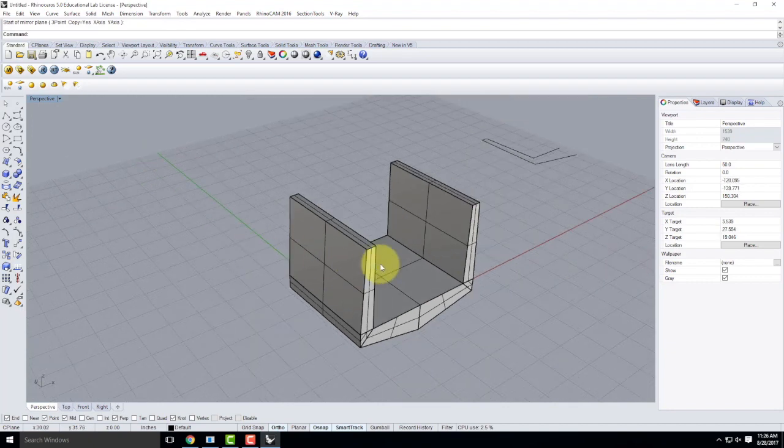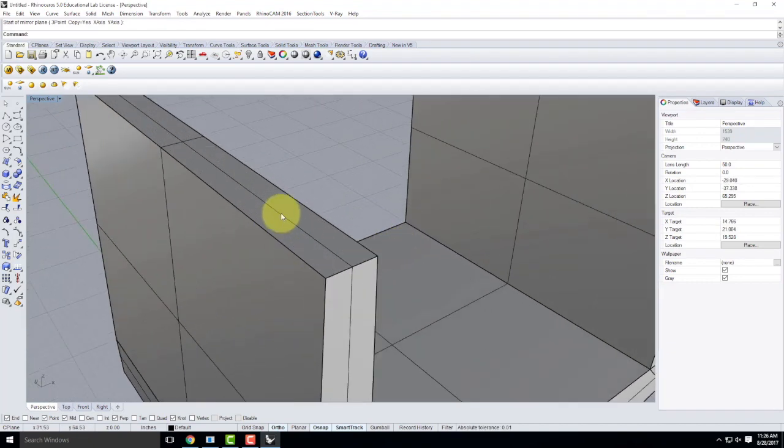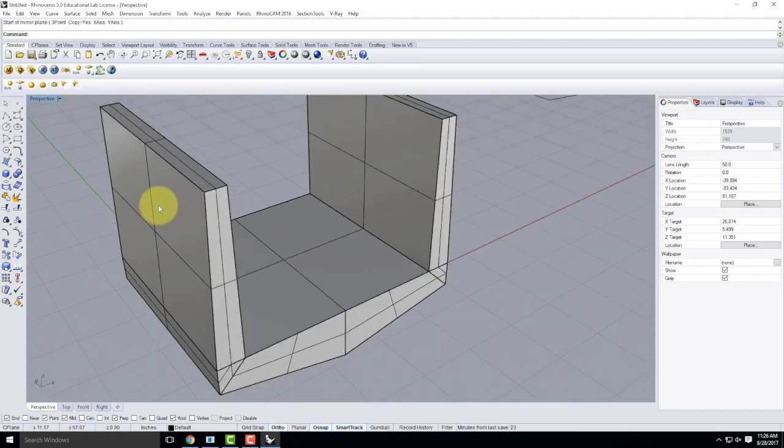Building the basic shape isn't so hard. It's the details that start to matter. What I want to do is I'm envisioning this as a piece of concrete. And generally, when you have two seams of concrete, there's some kind of a transition. You don't have continuous concrete to continuous concrete. There's a joint, and that joint is where cracking and stuff would happen. So it's called a control joint. I'm going to create that, or at least half of that, along these edges.